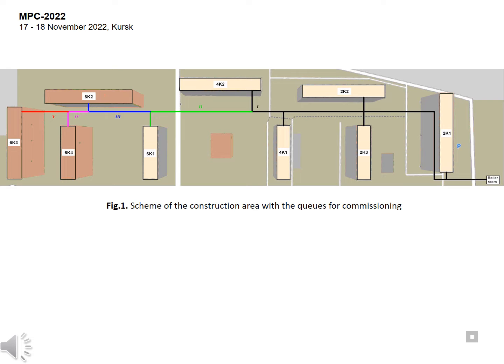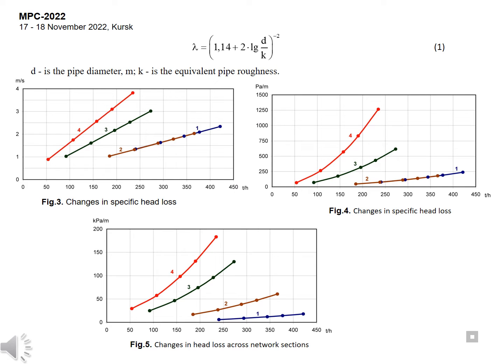Water heating networks were designed for prospective development under the condition of fluid movement in the area of a developed turbulent regime, as is customary in direct hydraulic calculation. When new consumers are connected to the existing network, the speed of water movement and pressure loss will change.